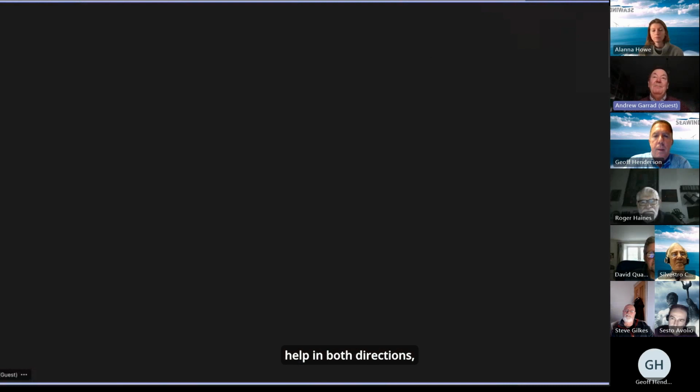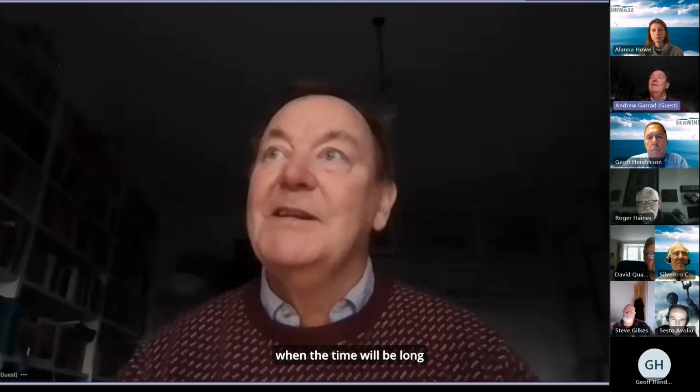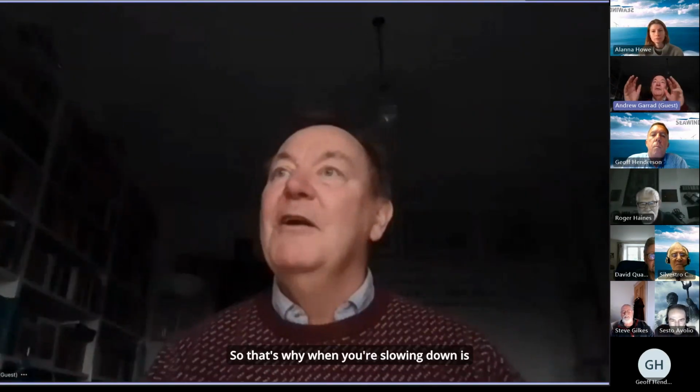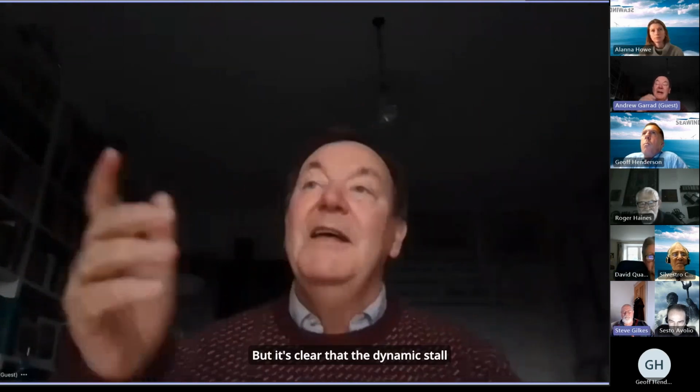I think what's going to happen here, the dynamic stall is going to help, but in both directions, going up and coming down, until the rotational speed gets low, when the time will be long enough to develop the vortex, leave, and then it'll stall. So that's why when you're slowing down is when you'll get this problem. But it's clear that the dynamic stall will be very helpful in keeping the flow attached.